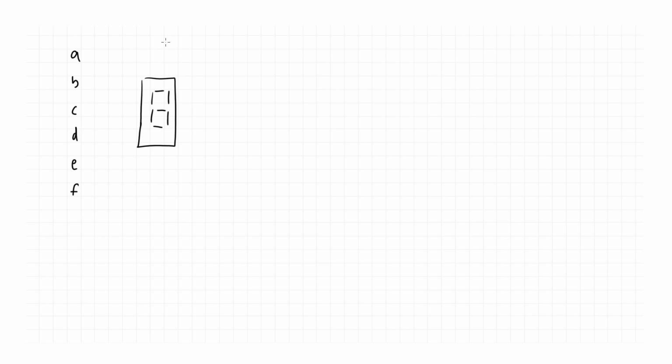And because hello is HELLO, 5 characters, and we've got a 3-bit count from the clock inputs, C, B and A, we had 3 opportunities to put other characters, but I chose to put blanks. You could have said hello and then 3 more characters. But anyway, that's not important. But what is important, I think, is to get some more 7-segment displays, because it's all very well it's scrolling through 1, but what if we had 5?